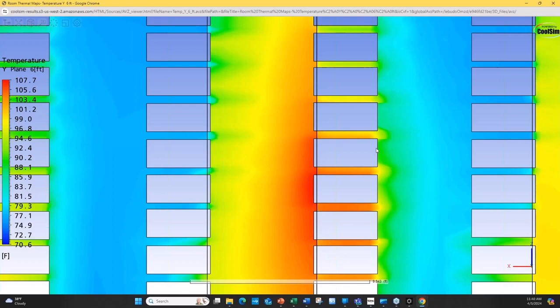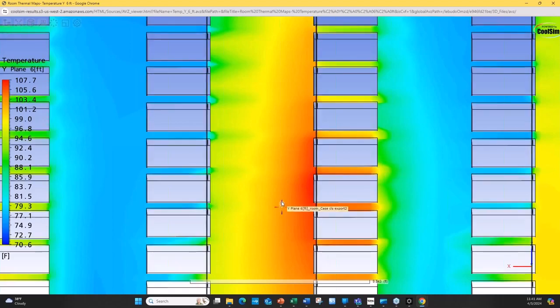Magnus, I was working on one of these for one of the national laboratories, one of the smaller data centers, and they had sent me thermal data. The only way I could get the thermal data to match the model data, the simulation data, to calibrate was to open up the leakage to almost 100%. I called them, and we did one of these reviews like this, and I showed it to them. I said, "You guys got to be leaking terribly." And they said, "Well, how did you know that?" Well, the temperature data told me that. They were measuring temperatures out here that are almost equivalent to what was over here, which means it has to be leaking pretty badly.